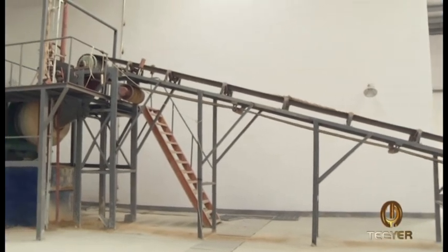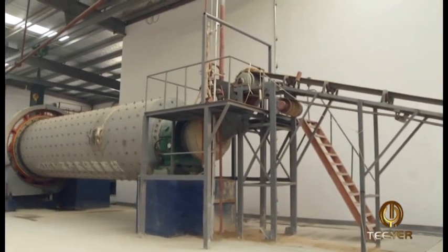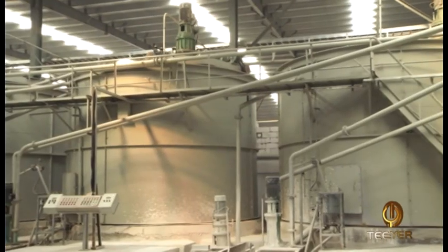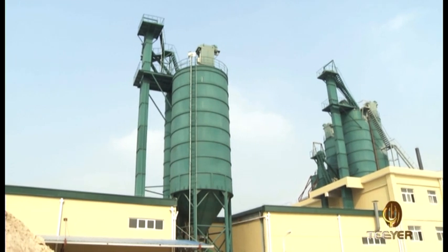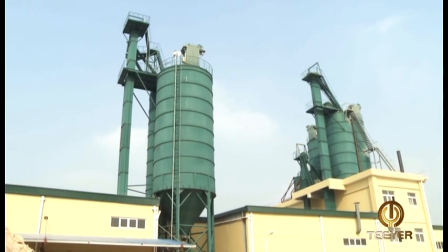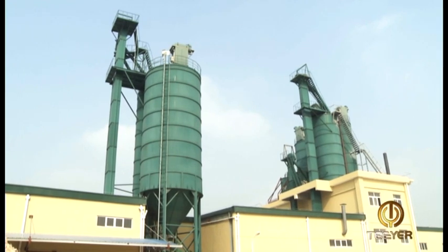Operation principle of autoclaved aerated concrete production. At first, pulverized fly ash or sand are ground through the ball mill and made into slurry stored in a storage tank. The cement and the lime which have been processed are respectively conveyed to the cement silo and lime silo.